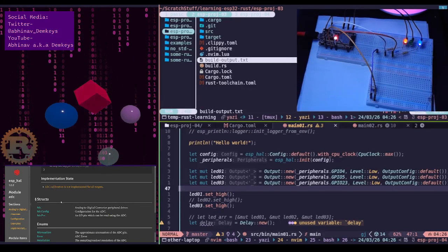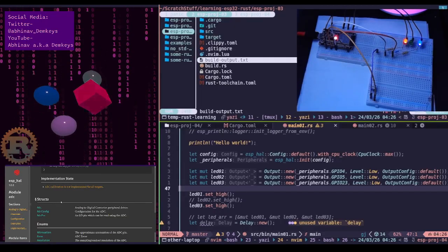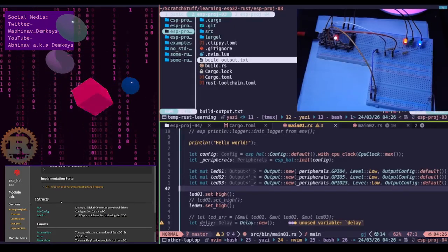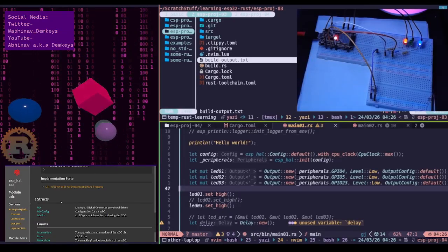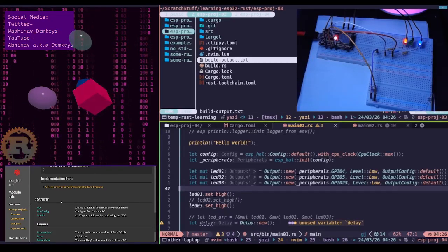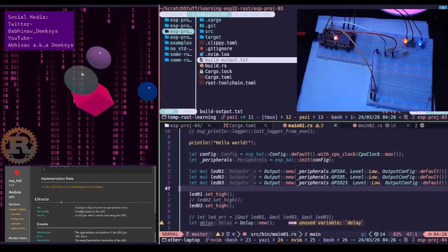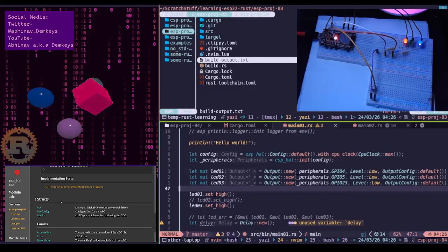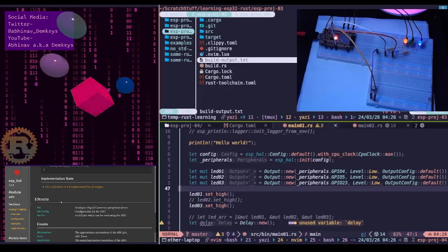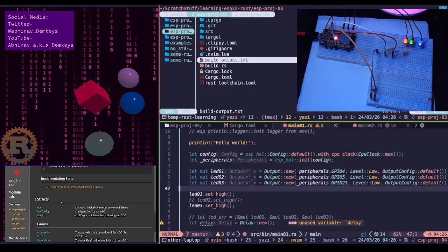Current limiting. Potentiometers can sometimes be turned into zero resistance without a fixed resistor in the series, and the LED would receive too much current and burn out instantly. Note, for your ESP32, make sure you are powering the pot with 3.3 volts, not 5 volts. Oh shit, I need to be careful of that, yeah.